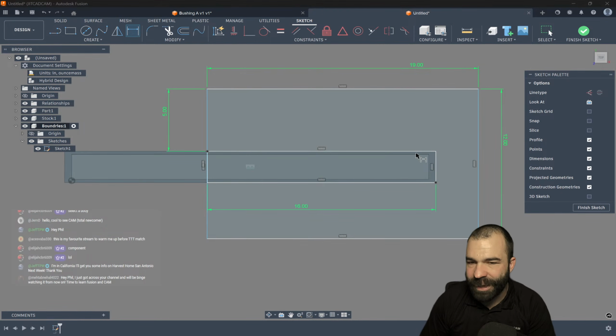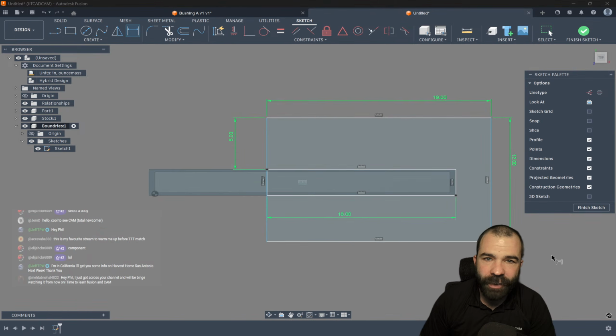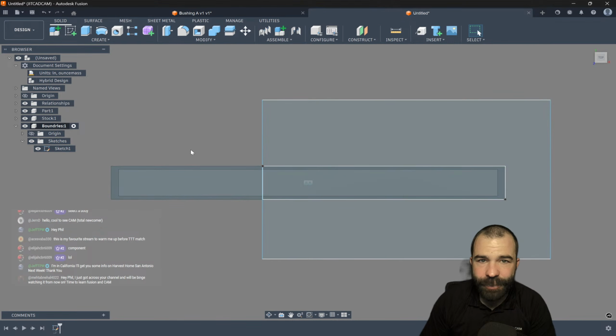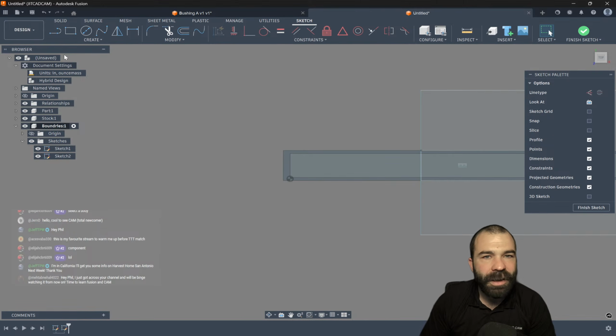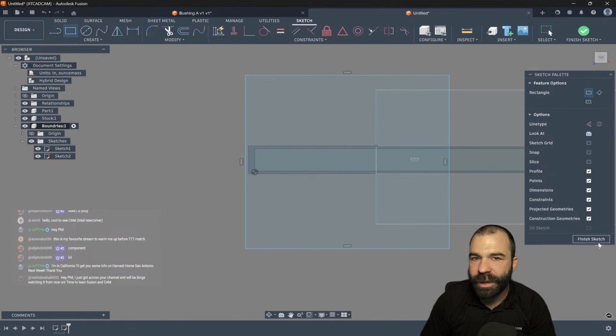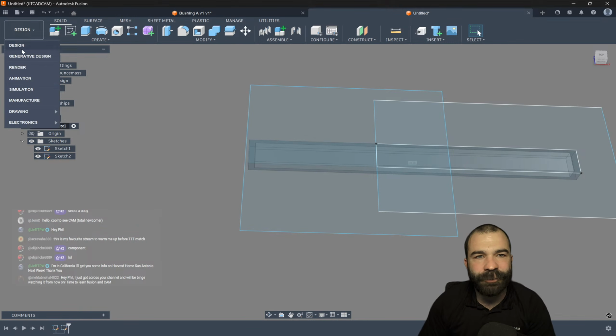The sketch that does matter is the one on our part, which is for our 2D scenarios only. And the sketch outside is for 3D toolpaths. Now, this is where I would personally, at some point, I'm going to have to slide this down my machine, right? I might make another sketch. Again, same surface. Maybe add my rectangles down here at the other end. Again, whatever your boundary is going to be, we're going to just go ahead and make a generic one. This just makes it easy for setup 1, setup 2. That's all I'm doing, guys. I'm thinking a little bit ahead of myself to make life easy.